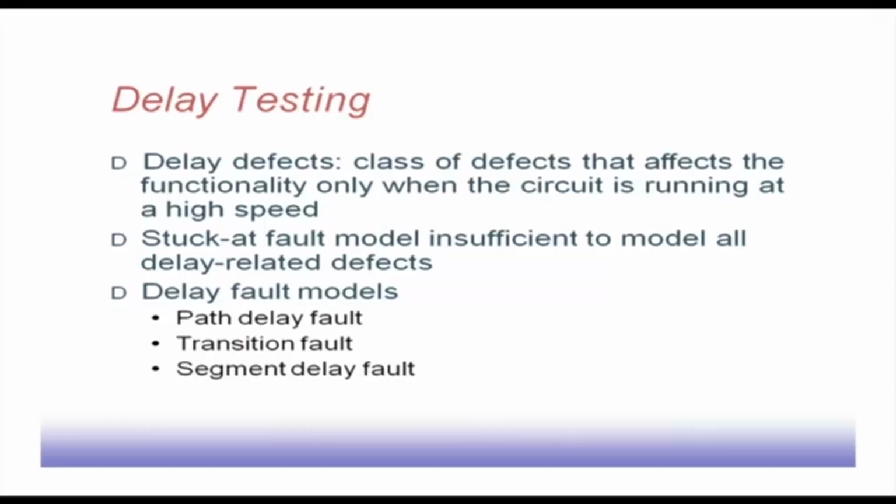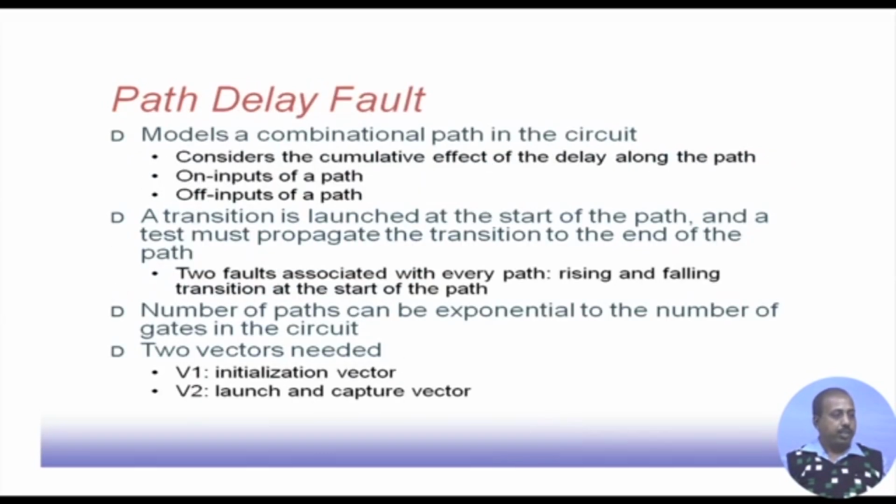Then for delay testing, we can have delay defects, but stuck-at faults and delay defects are different. Delay defects are faults that affect the functionality when the circuit is running at high speed. This is there because of the delay of various parts. So, the stuck-at fault model is insufficient to model all delay faults, and for delay faults we know there are several models like path delay fault, transition fault, segment delay fault, etc. But simulation-based ATPGs are not very good for delay testing. So, for delay fault testing, we need a different type of test pattern generation.